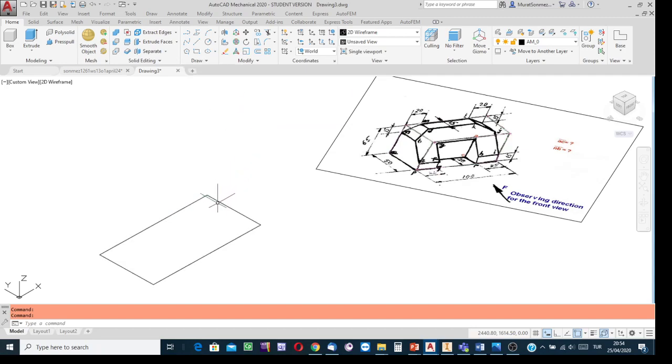Okay, if the rectangle was created, line by line using the piece of line facility, then yes, it would be a mess to apply region definition process. But since I created this rectangle using rectangle creation tool, it is okay. The surface bounded by the rectangle is a region. Can directly apply extrusion. Okay, started the extrusion process.